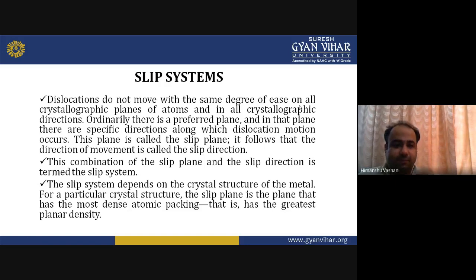Slip systems. Now slip systems are important when you are studying dislocations. How they are important, we will study in the coming slides. Dislocations do not move with the same degree of ease on all crystallographic planes of atoms and in all crystallographic directions.